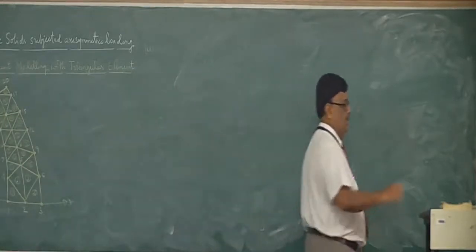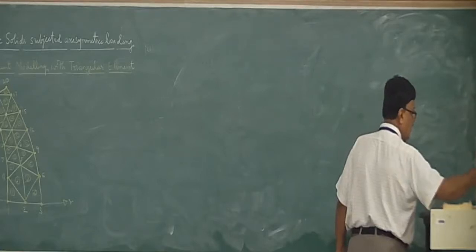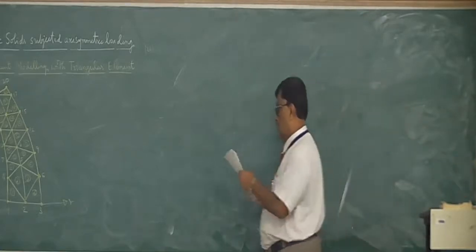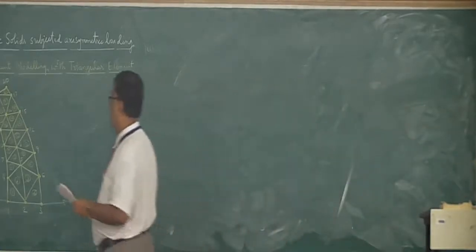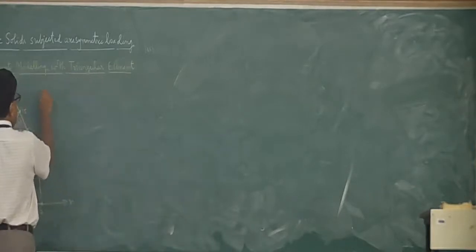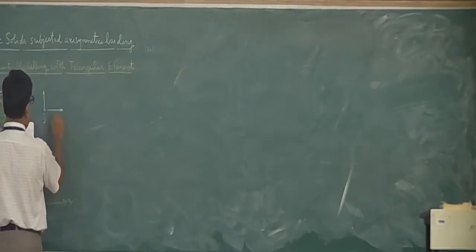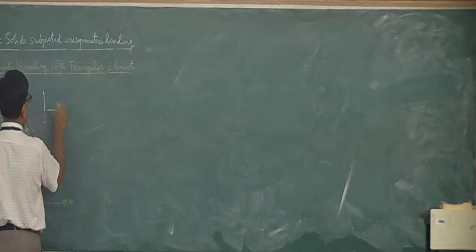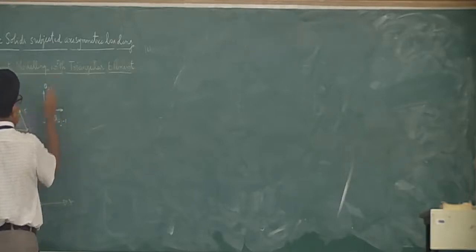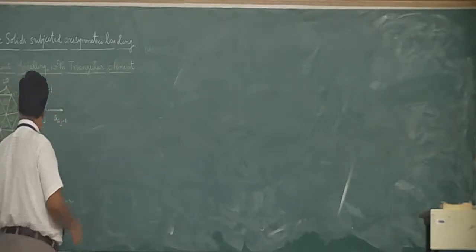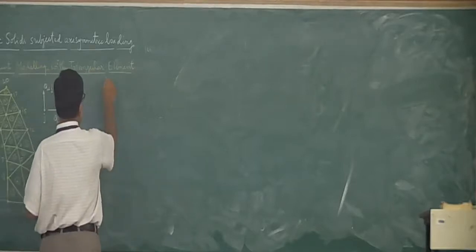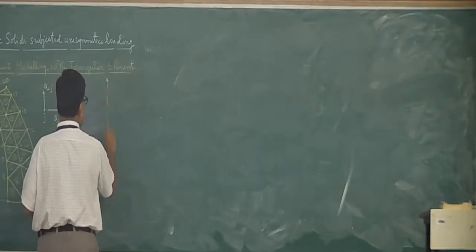You can see there, this is what we call the finite element discretization. Always remember the node numbers have the same relation. Here I have used what we used for the CST element, which is 2j minus 1 and 2j. So if you look at the layout, for example, let me show you how exactly this looks.